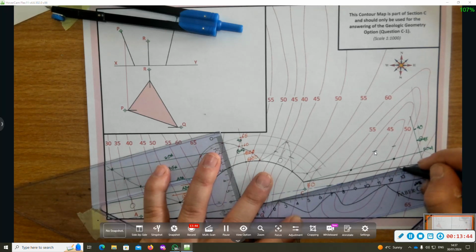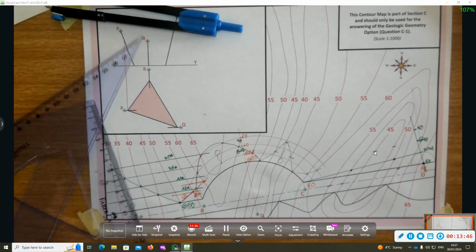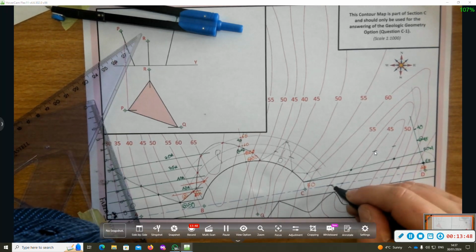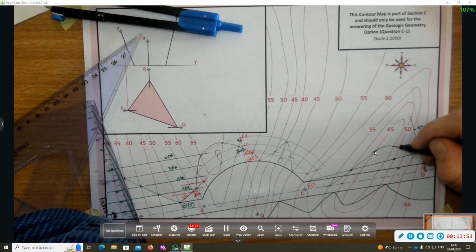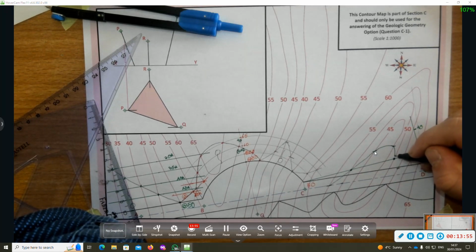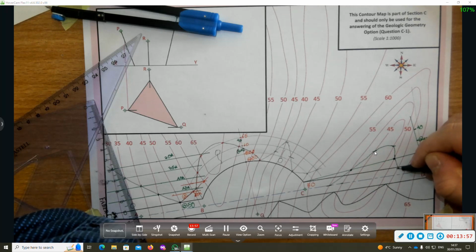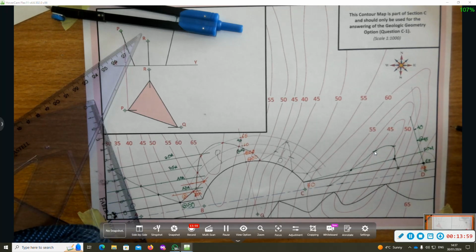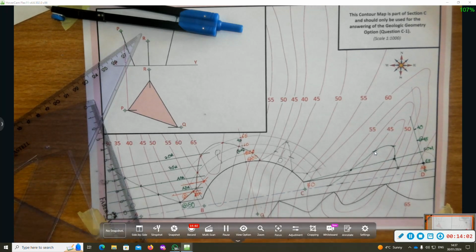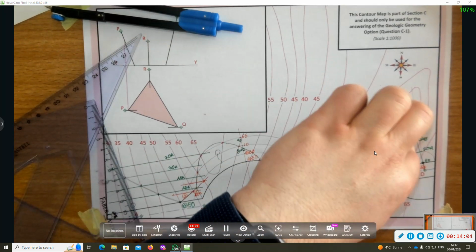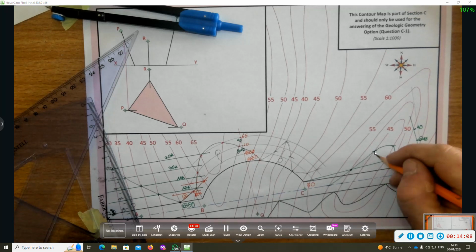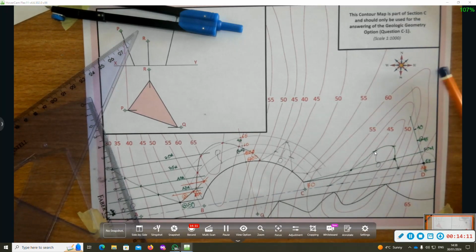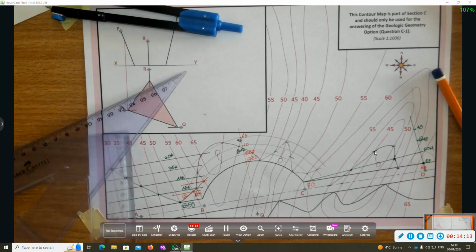So they're only constructions. So I'm going to freehand sketch them in nice and lightly. And now I'm going to have a cut and a cut here because this is the embankment. So the tadpole always swims up the hill. So the cut, you put the cone at the lower end of the road.